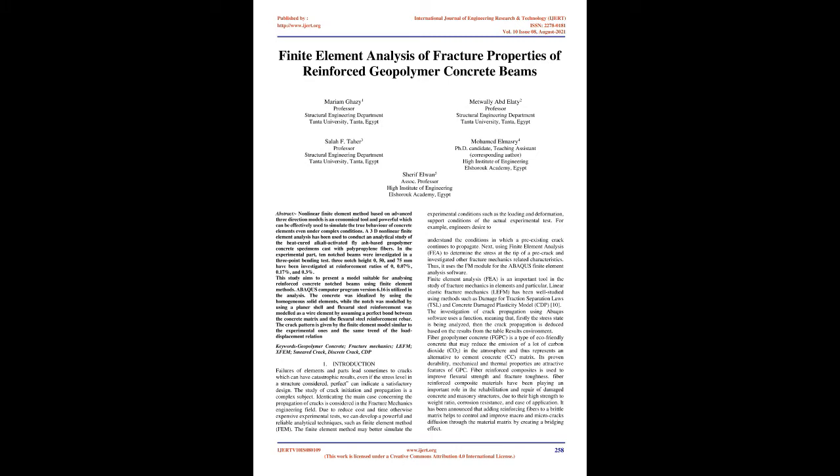A 3D nonlinear finite element analysis has been used to conduct an analytical study of heat-cured alkali-activated fly ash-based geopolymer concrete specimens cast with polypropylene fibers. In the experimental part, 10 notched beams were investigated in a 3-point bending test. 3 notch heights, 0, 50, and 75 mm, have been investigated at reinforcement ratios of 0, 0.07%, 0.17%, and 0.3%. This study aims to present a model suitable for analyzing reinforced concrete notched beams using finite element